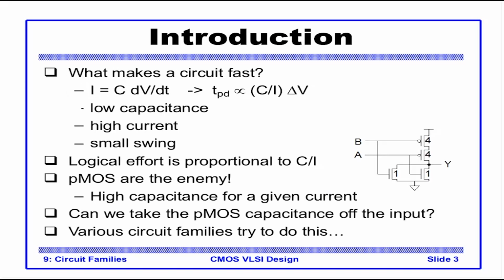Now, what makes a circuit fast? There are three parameters for comparing different logic families. One, obviously, is the area, that is, the transistor count. Second is how fast or how slow the cell is. Obviously we want faster. And third is the power consumption. In earlier technologies or smaller chips, power consumption was not a big issue, but power consumption is now one of the most important factors, even more so when we consider that a lot of devices that we use are battery powered. So obviously we want something very economical in terms of power.